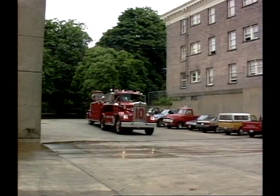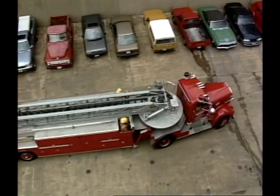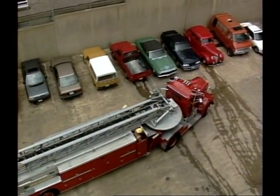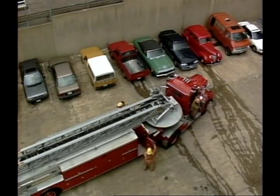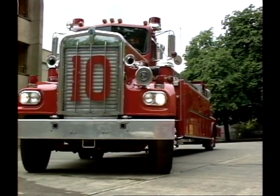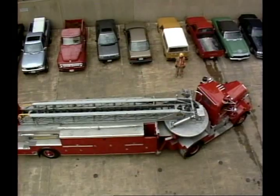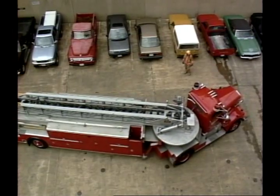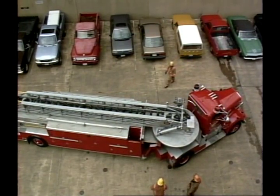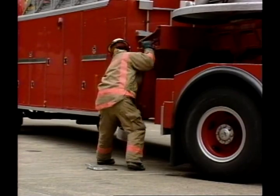One way to put the apparatus into the desired angle position is to stop so that the turntable is right next to the intended objective. Then cut the wheels sharply toward the center of the street. This will bring the truck slightly forward. The tiller wheels should be cut sharply toward the building as the truck backs up a little. When the desired angle is achieved, apply all of the brakes and proceed with deploying the stabilizers.